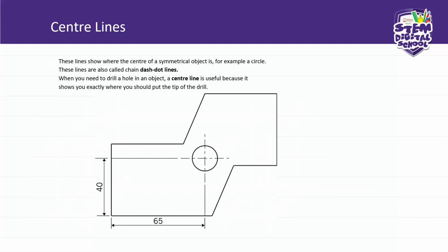On this drawing, I also want you to see the dimensioning, how we write our measurements. We don't write the units for the measurements, but we rather write the value. Look on which side of the arrow the value is. These dimensioning lines show us the 40 millimeters.